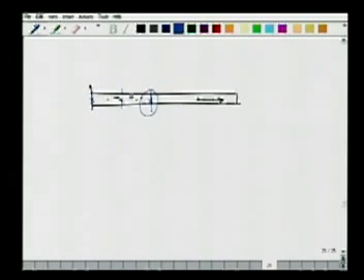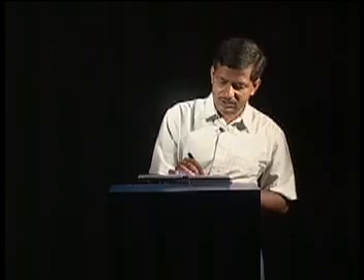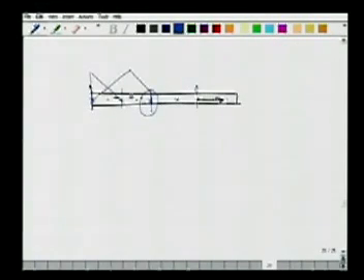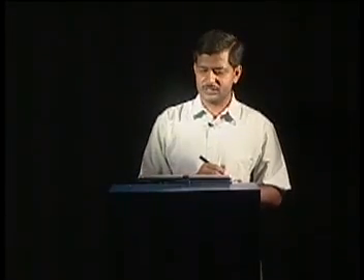This is one material, this is another material. Another node I can put here, and another node has to be at the point where the concentrated load is applied, and so on. This way I can define the partitioning of the domain, and based on the partitioning of the domain, since these functions phi i are defined with respect to these nodes, I can define what these functions phi i are, and go ahead and construct my approximate solution to the problem of interest.